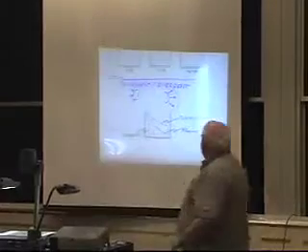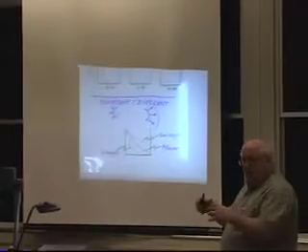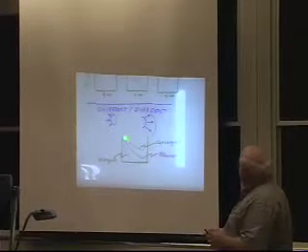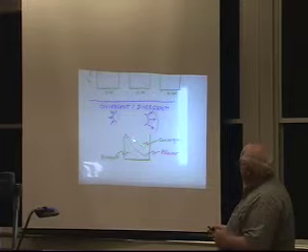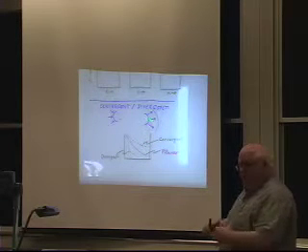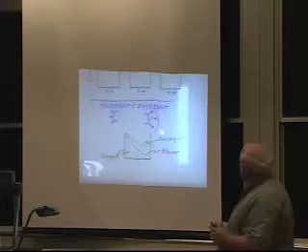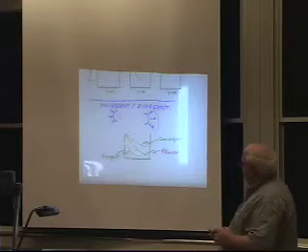Now, there are complications, as we said. If the heat flow is convergent, I'm heating a cylinder from the outside, and the heat's concentrating as you get towards the center, then you'll have an effective Fourier number that's more like the thin film solution. If it's divergent and I'm heating from the inside of a pipe and the heat's going outward, I have to heat a larger mass at a greater radius, and that's more like the thick film solution.